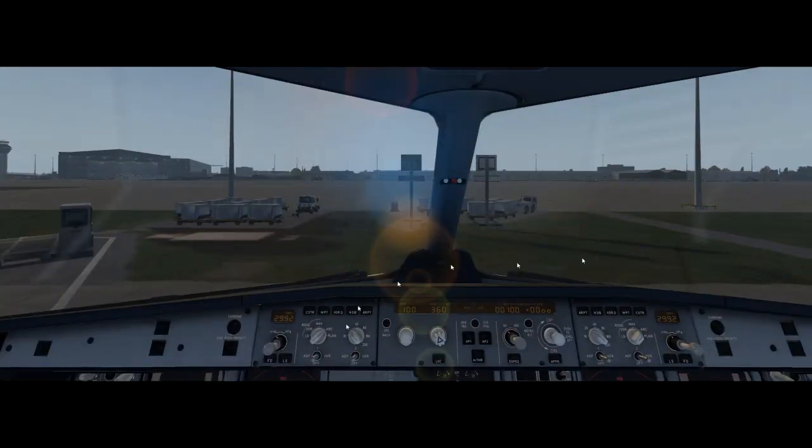Anyway, it's a standard layout of the cockpit. On the top, hang on, let me get here. On the top you've got the MCP on the glareshield. Starting over on the left hand side, you've got the chrono, which is your clock, side stick priority, QNH, then you've got your nav displays, so whether you want ARC, plan, nav, VOR or a landing display.